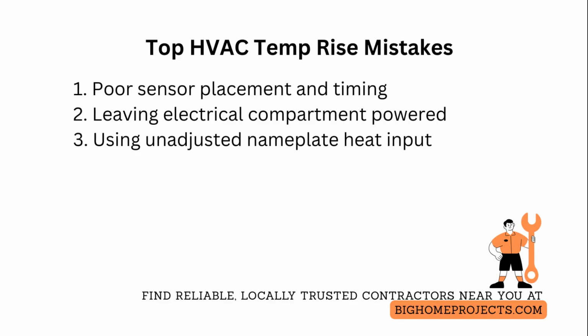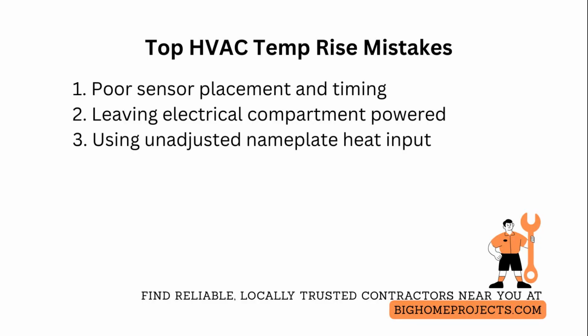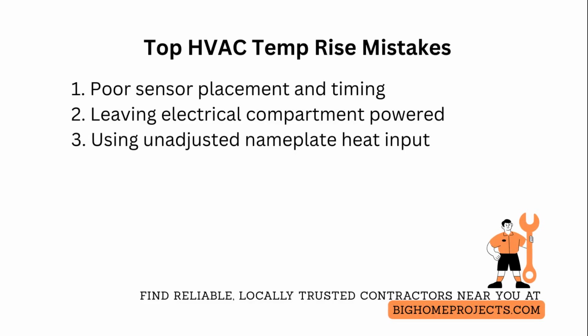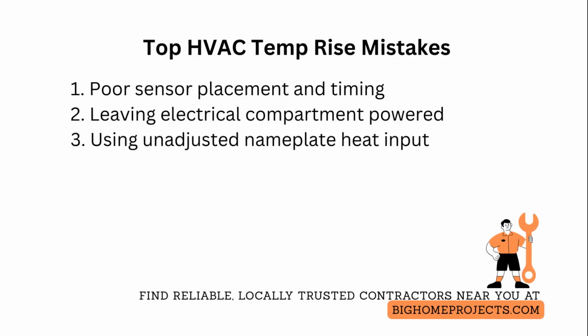One of the top 3 common mistakes is inaccurate temperature rise measurement due to poor sensor placement or short sampling time, which causes wrong airflow cubic feet per minute readings and leads to improper system tuning. Fix this by averaging 5 minutes of stabilized readings from centerline probes and marking probe locations for reproducibility.